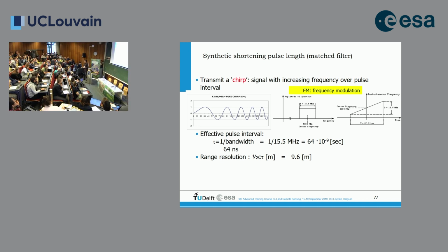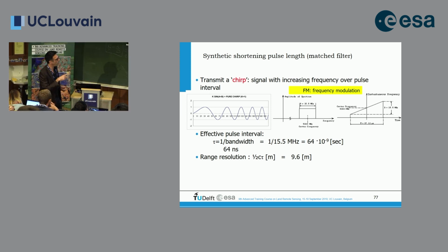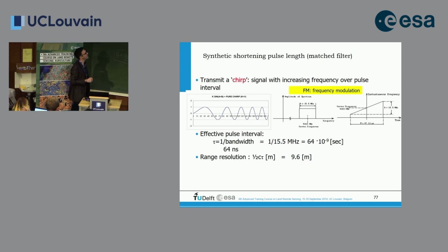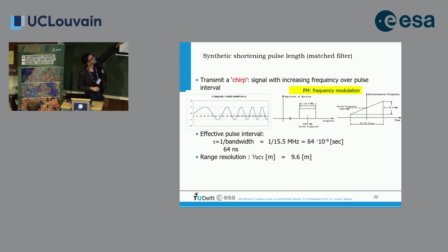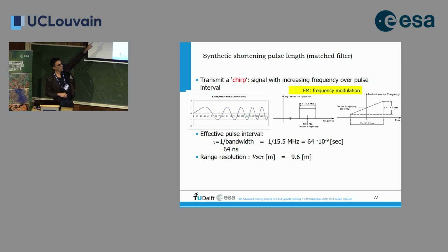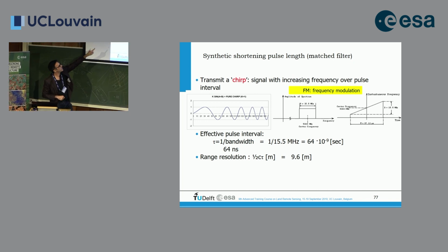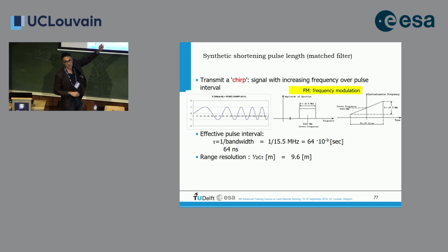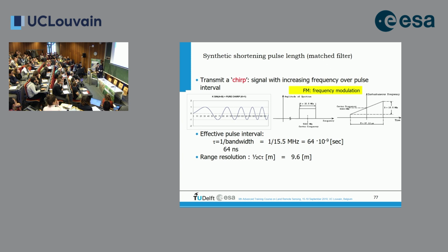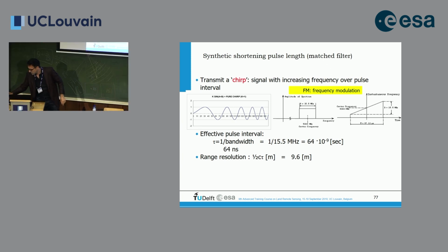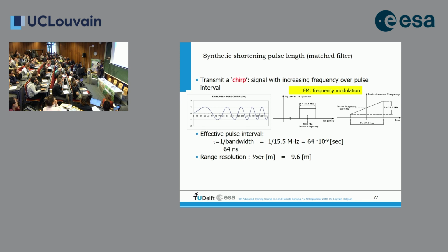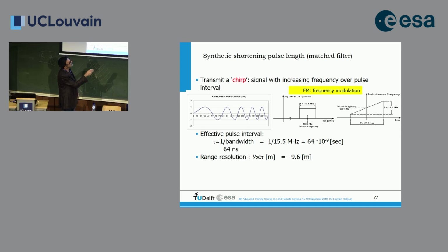So the satellite is constantly kind of transmitting a chirp, like the birds do, right? They chirp. And it's continuously doing that. And so you see that in the left figure here, so going from the low frequencies to the high frequencies over on the right-hand side. In the middle figure, you see that in a frequency graph, right? So we have a certain center frequency. Let me use my pointer. Center frequency here, this is 5.3 gigahertz, so this is C band, 5 centimeter wavelength.